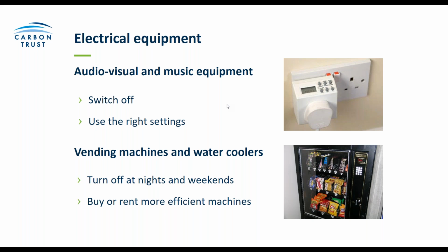And also things like vending machines and water coolers, again, are things that only tend to be necessary while the school building is actually occupied. It's always worth looking at, can these things just be put on time switches so that they switch off at the end of the school day and come back on again in the morning, and also switch themselves off at weekends and in the school holidays, where you can again get quite good savings there.